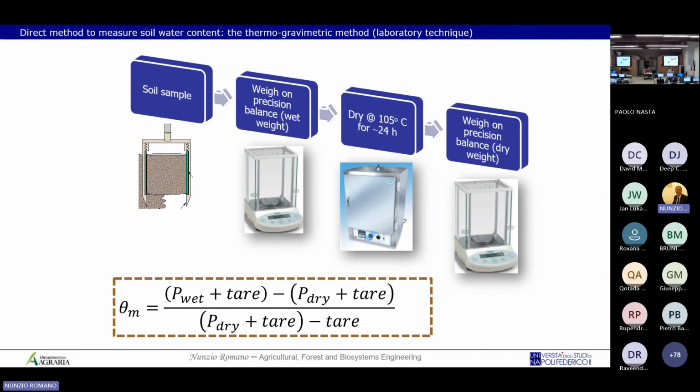And many decades ago, many laboratories were involved to find the right temperature where the free water evaporates. They collected all this information for most soils, different kinds of soil textures, and they realized that this free water just evaporates in a range between 100 centigrade and 110 centigrade.